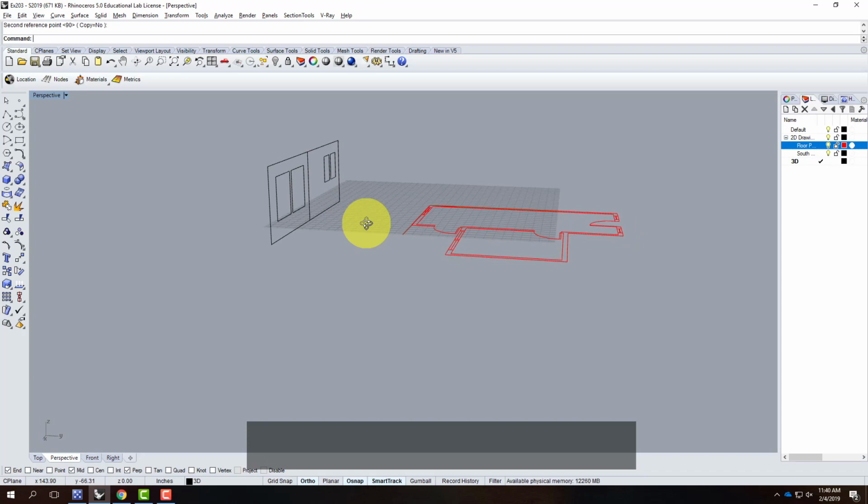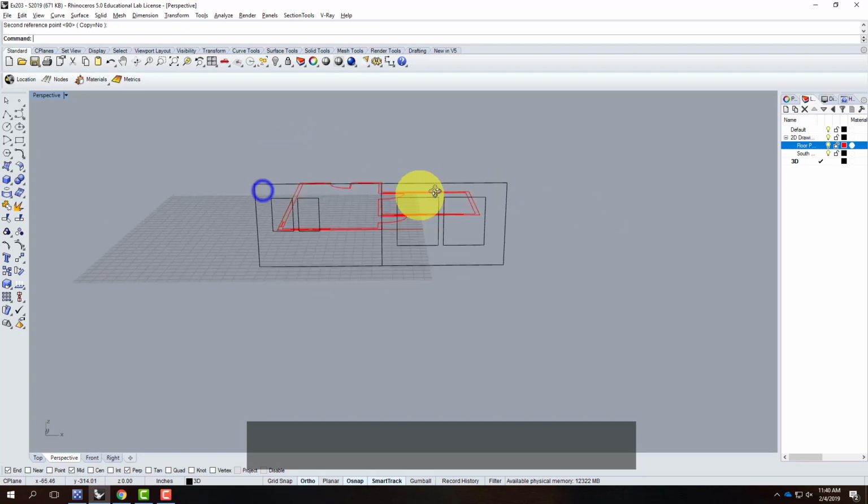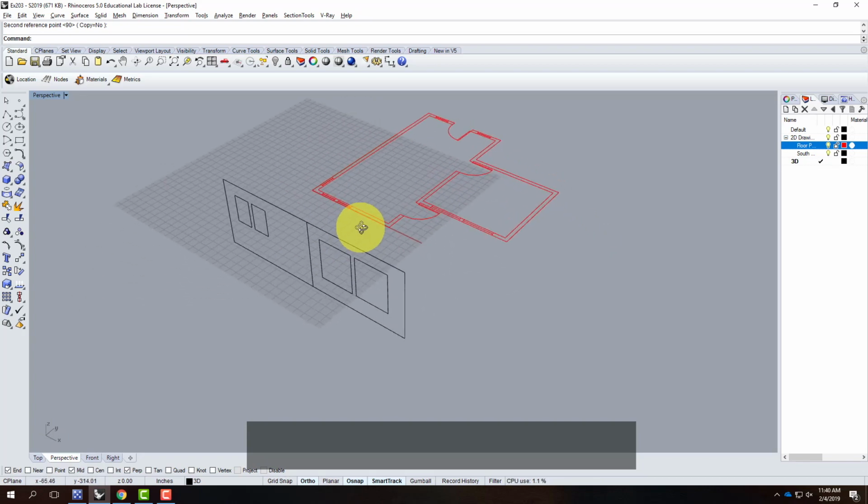You're still in the top view. So double click where it says top in the left corner of the viewport. It's kind of gray. Double click that, and then double click on where it says perspective. And that'll get you into the three-dimensional view so you can see this happen. So now that I have that standing up, that's a good thing.